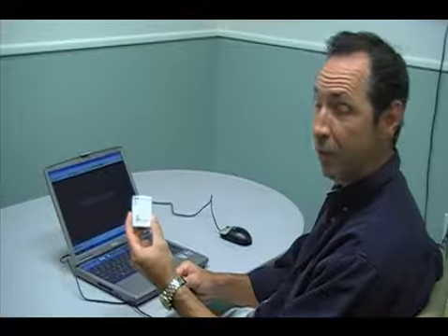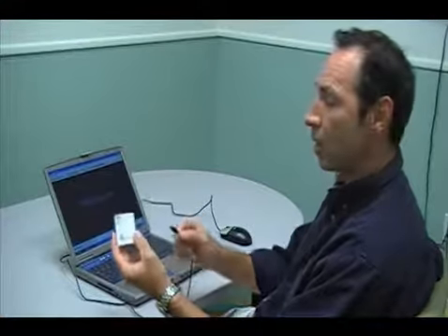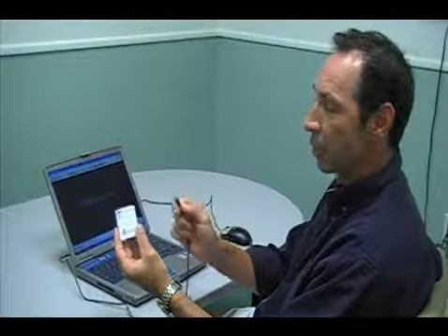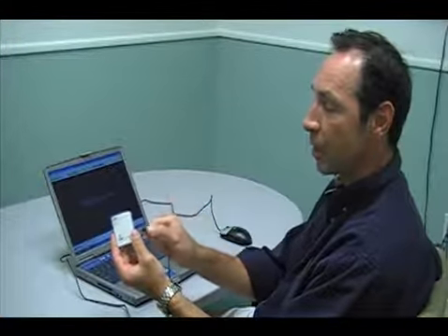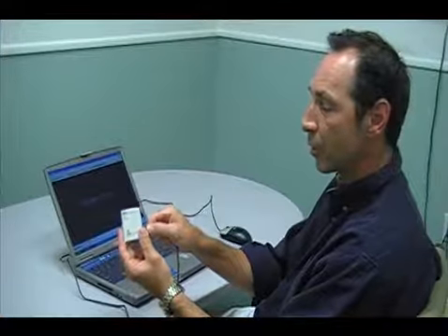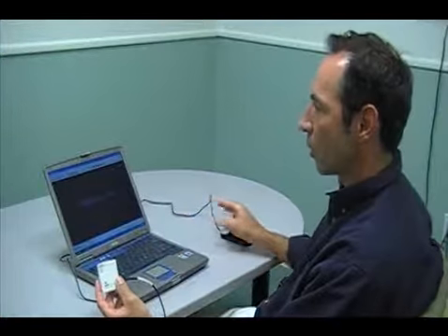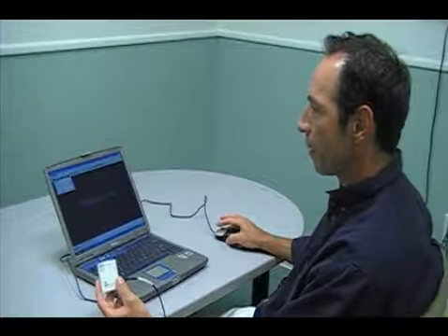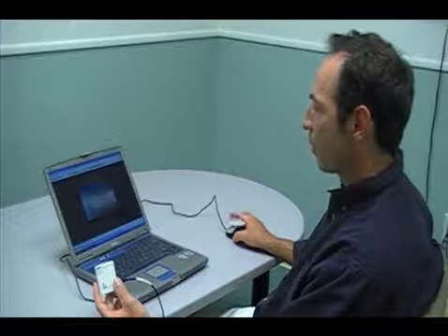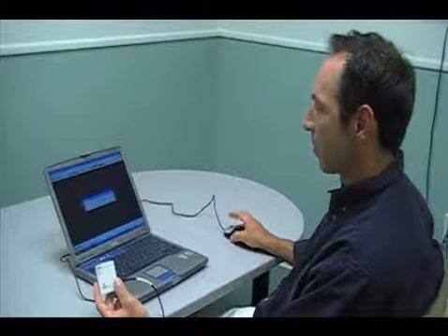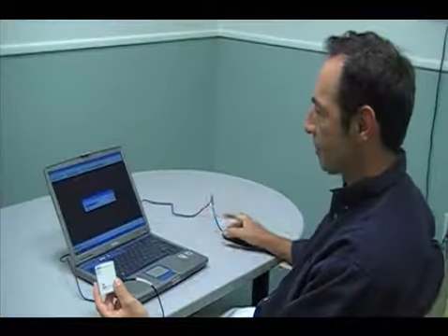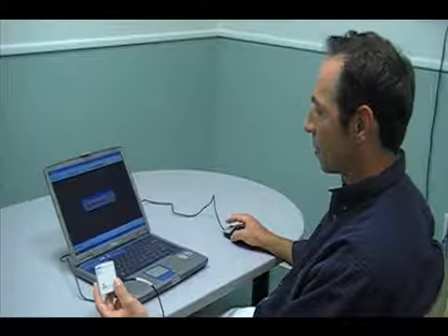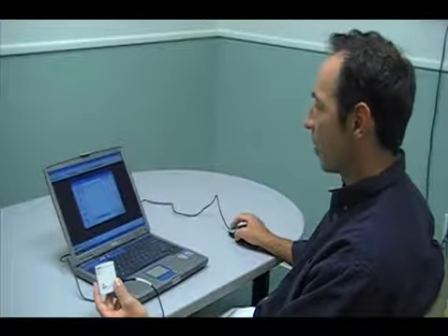Now that we've been collecting data for a couple of days on our compressor, I brought the logger back to the computer. I'm going to offload the data and see what we got. Offloading data is real simple. You just simply connect the USB cable to the USB connector on the side of the logger. Software recognizes it. Click readout. It's offloading the data. And save the file.